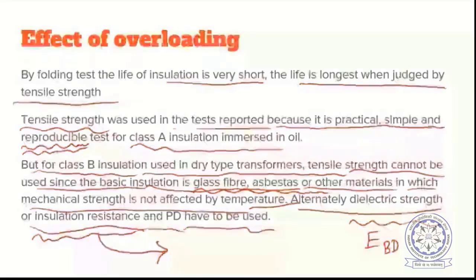But it won't happen. If the resistance decreases, the insulation strength goes down, or it is becoming like a conductor. Of course, to become an actual conductor it takes a lot of time, but its resistance decreasing means the conducting nature is coming. Ideal dielectrics are expected to be insulating. The resistance should ideally be infinite, and our conductivity should ideally be 0. So this resistance is another parameter which can indicate the level or condition of the insulation at any given point of time.